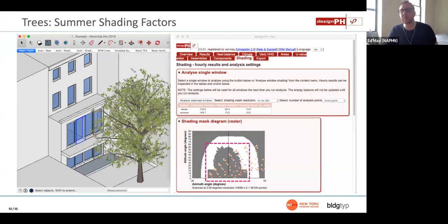So you're going to be able to get building footprints that way, and then extrude those up. If you need to build out the neighbors right next door in a more detailed fashion, you just do the old-fashioned thing: go on site, take photos, and try to build that as accurately as possible. But that would only be for if it's really critical and it's right next to the building. In general, we can get almost all that we need from those OpenStreetMap GIS data sets.